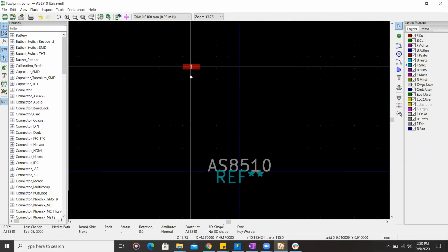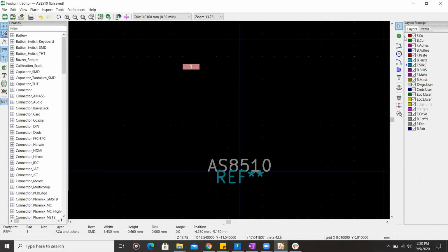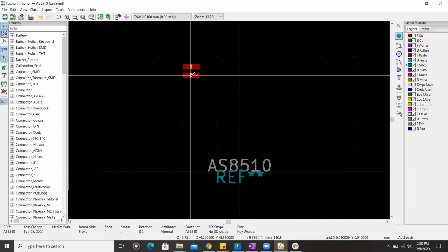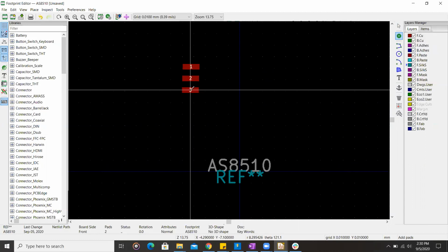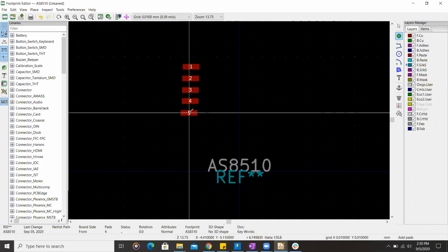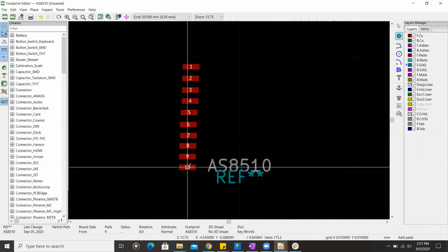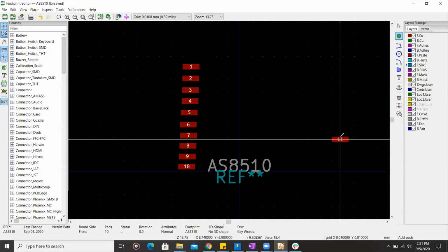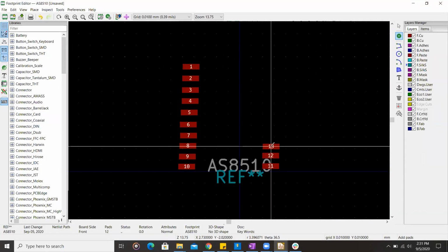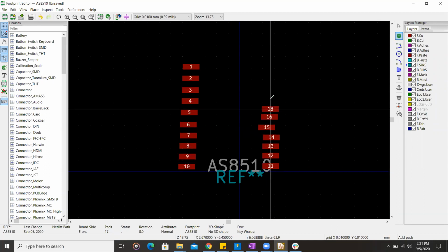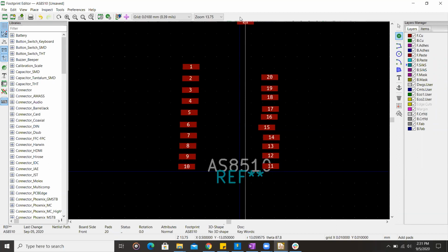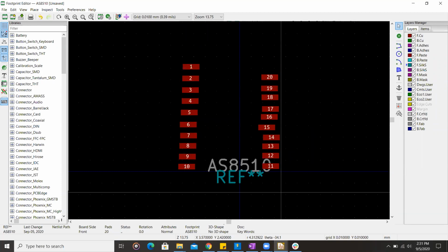Okay, so if you press C, and then now if you go and click add pad, notice that it copies the exact pad that you made before. So for now, I'm just going to arbitrarily lay out 20 of these because that's how many we need. The good thing about this software is that each time I want a pad, I don't need to go here. I can just click, and it makes it a lot easier to work with, and it definitely simplifies having to do everything. So now you have the 20 pads that you're working with.